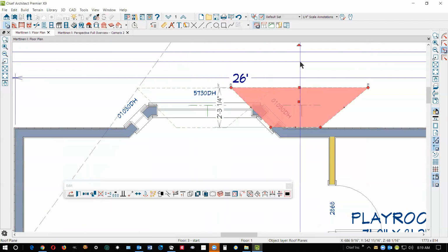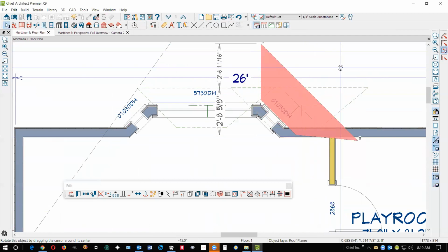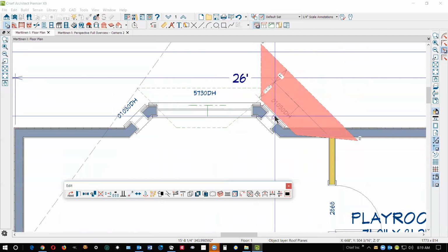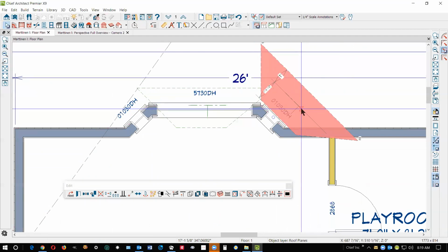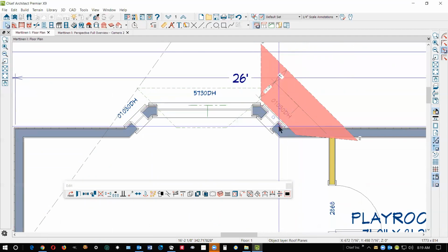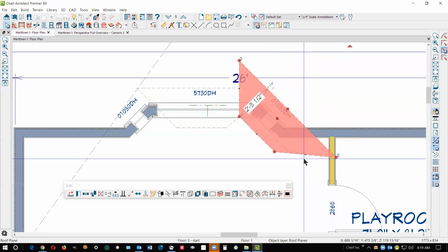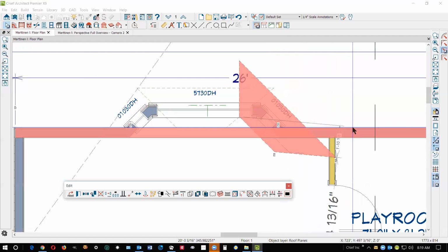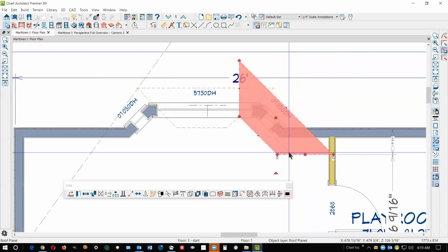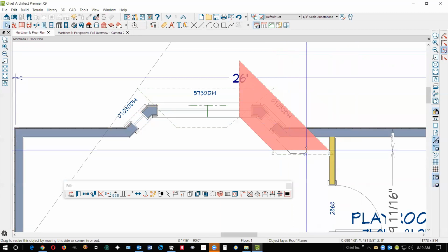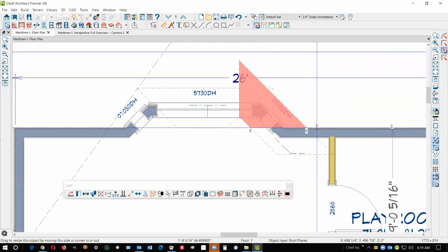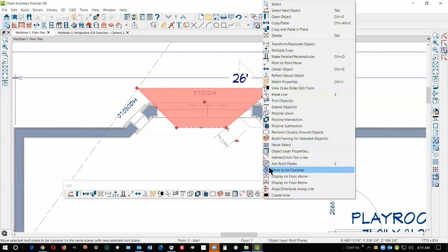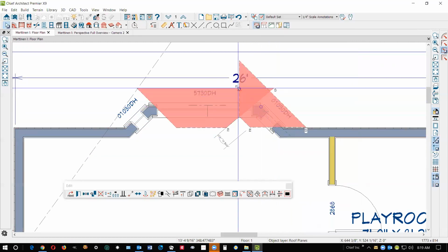I'm going to copy here, turn it to 45 degrees, and then use point-to-point move to move the baseline from where it is out here to the edge of the framing where it's supposed to be. And then we can take this edge here and parallel it to this wall, or perpendicular, either way. Put it on the outside. And then these two edges, we'll join them.